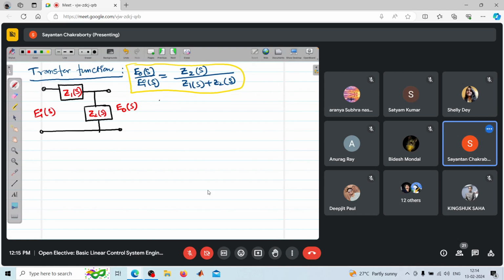In this manner, each and every calculation will become very easy. Say, for example, suppose we have an RC circuit. In time domain, it is written as R and C and ei and e0. So I can readily convert it to its frequency domain representation as Ei, E0, capital meaning in s domain, R and 1 by Cs.